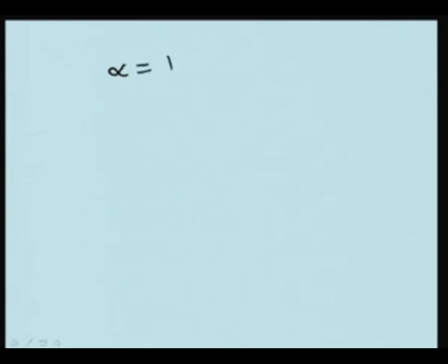Let us say that in a typical motor, when you start a motor, you get a torque, and this torque is proportional to I, that means K times I current, and this is K times V applied voltage minus KB omega divided by R, where this is back emf.